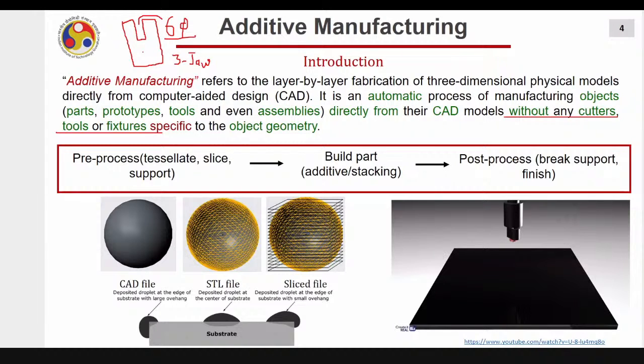and a 6 mm diameter drill bit tool. Now, if I change the geometry, and the geometry is no longer a cylinder, it is a cuboid, and also the diameter has changed. Assume that this diameter is now 8 mm. In that case, as it's a cuboid, a more appropriate fixture to hold it could be a 4-jaw chuck. A 3-jaw may not be sufficient, may not be very optimal. And also you need a different tool. So you saw that I slightly changed the geometry, and I required different tools in the conventional process.